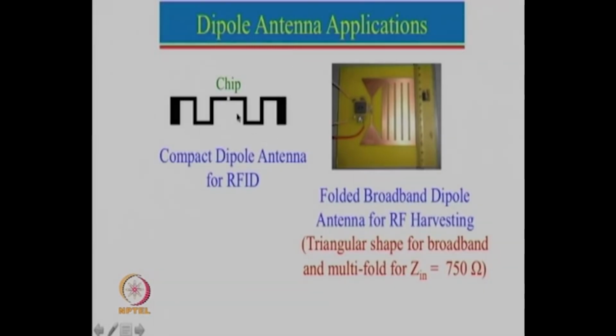Of course, optimization of these shapes is important, because efficiency of the antenna does depend upon how these things are bent. You can even think about this here. Let us say the current is 0 here and current is plus maximum here. So this plus maximum goes over here, and then here. Now this is a plus here and this is also a plus here, but this current is going down, this current is going up. So these two fields will try to cancel each other. So it is not arbitrary that you just put anything and it will work. No, it will probably fit in that particular area, but it may not be a very efficient antenna.